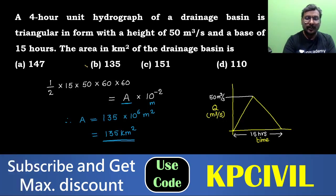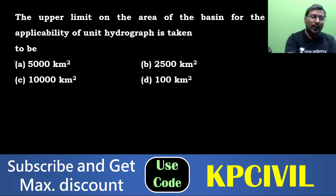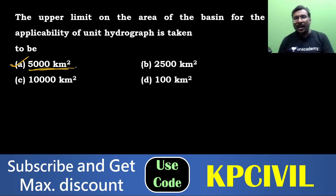So what is the answer? Option B is the answer. 4-hour unit hydrograph, area 135 kilometer square. The upper limit on the area of the basin for the applicability of the unit hydrograph is taken to be, as I mentioned in the previous session, applicable up to an area of 5000 kilometer square, not more than that.